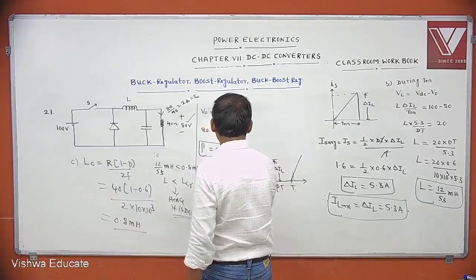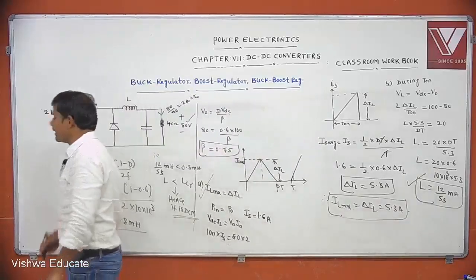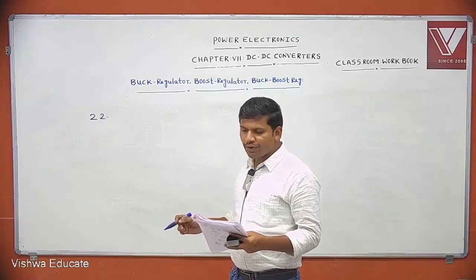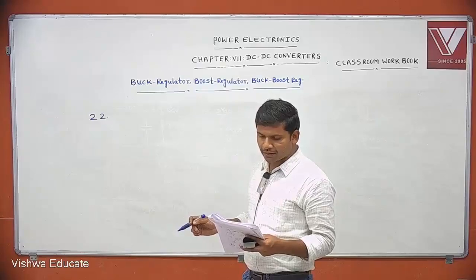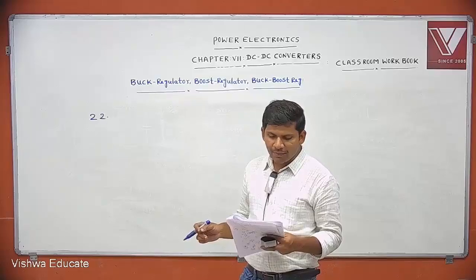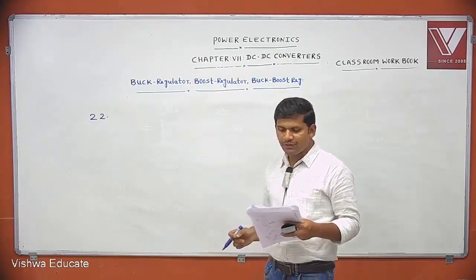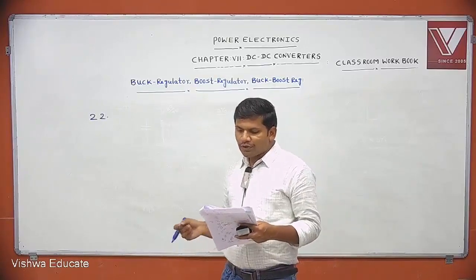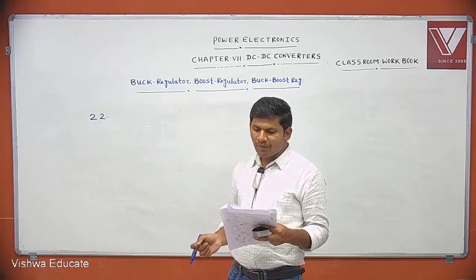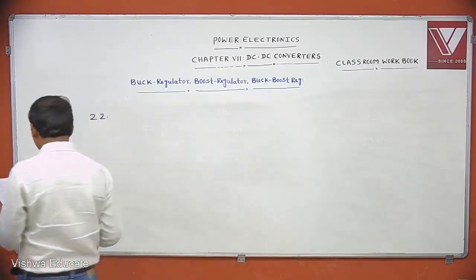Concentrate on how to calculate critical inductance. A DC to DC converter shown in figure is charging a battery bank whose voltage is constant at 150 volts. B1 is another battery bank whose voltage is at 50 volts. The ideal switch operates at switching frequency 5 kHz with a duty ratio 0.4. Once the circuit has attained steady state and assuming diode to be ideal, the power transfer from B1 to B2 will be dash.